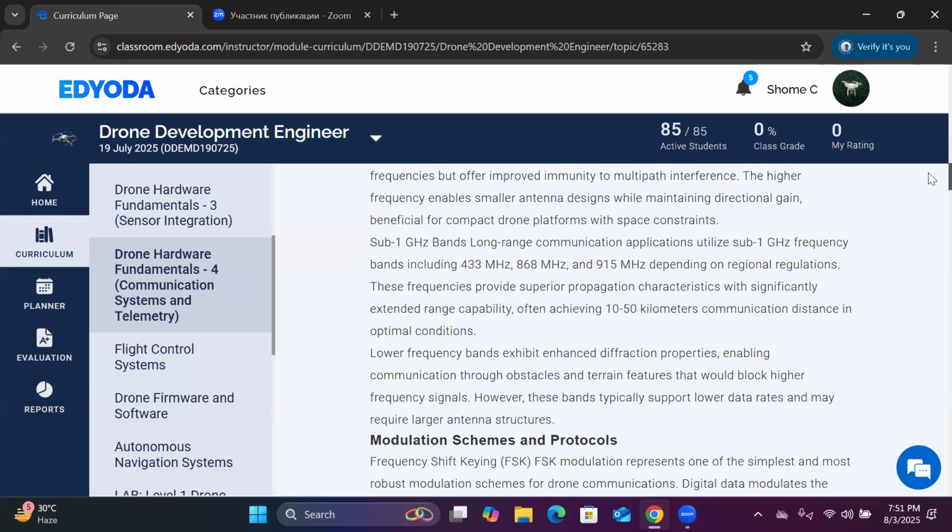See, for the knowledge of everybody, whenever you are reading a data sheet for any kind of wireless LAN module transmitting at a frequency of 2.4 gigahertz or 5.8 gigahertz, you will not see only one frequency band there. You will see multiple, different frequency bands there. Why is that important? Because whenever the modulation comes, it will modulate the frequency. It will generate the harmonics.